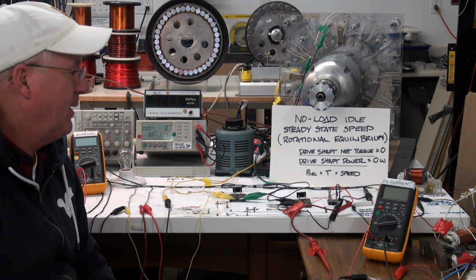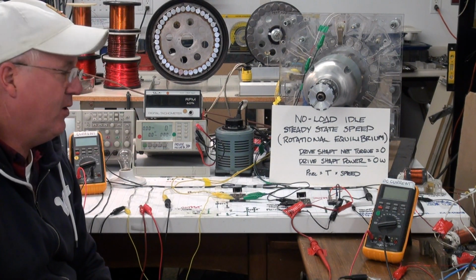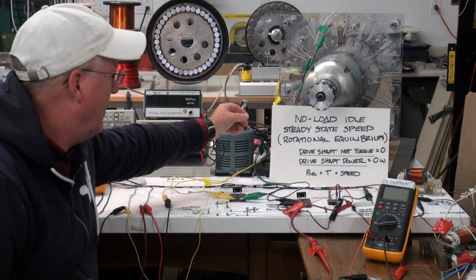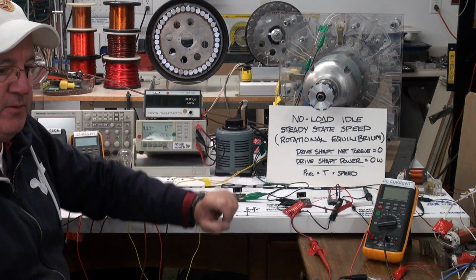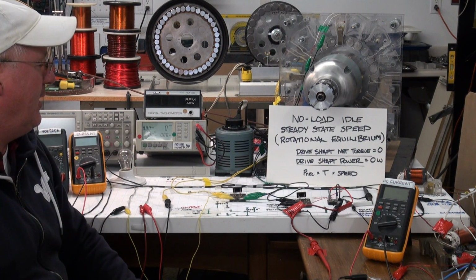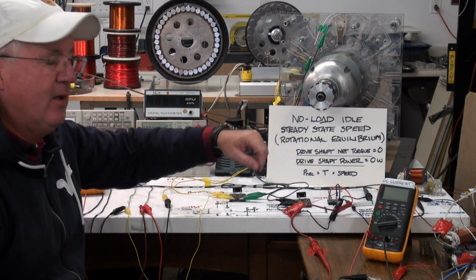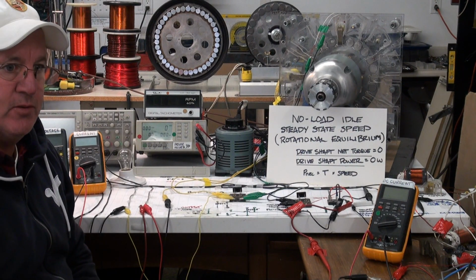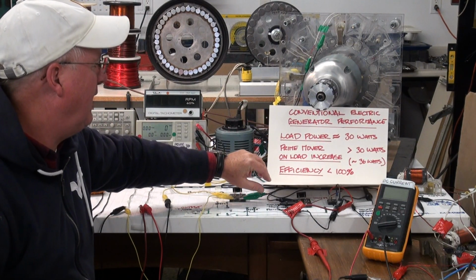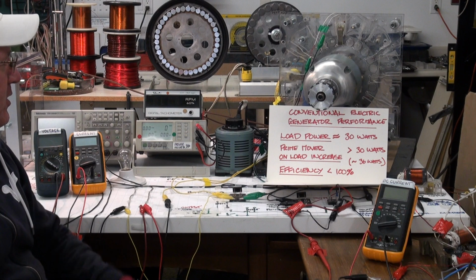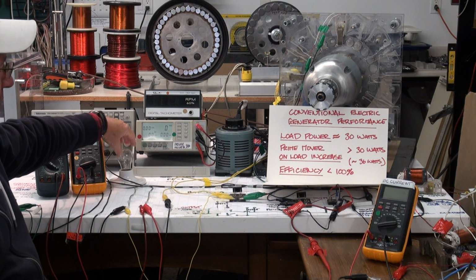So the first step is to bring the system up to rotational equilibrium. At rotational equilibrium, the net torque in the drive shaft is 0, and the mechanical power in the drive shaft, which is the torque times the speed, is also 0. So then what I'll be doing is placing the conventional generator coil that's in the prototype onto the load here,